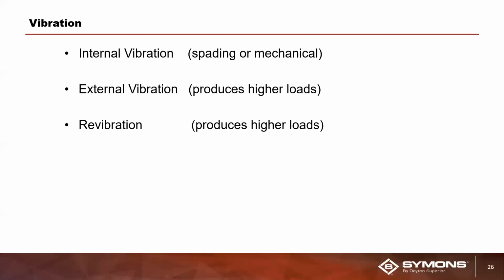External vibration is only recommended on heavy duty steel forms like a precaster would use, primarily because external vibration shakes the form system, sends a wave through the form system, creating a vibratory pulse. What happens is it shakes the form, vibrates the concrete, removing the air off to the side and helping it escape up through the sides between the forms and the concrete.